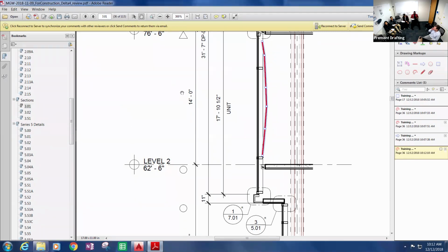Exactly. And then because I've got the intermediate horizontals, I'm not really worried about this light of glass deflecting more than 3/4 of an inch. So I still have to maintain that. Even if I can allow for the metal to go over the L over 175, each individual light of glass can still be 3/4.